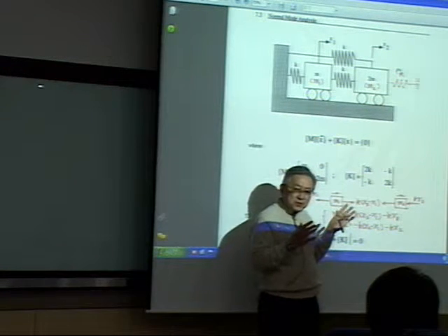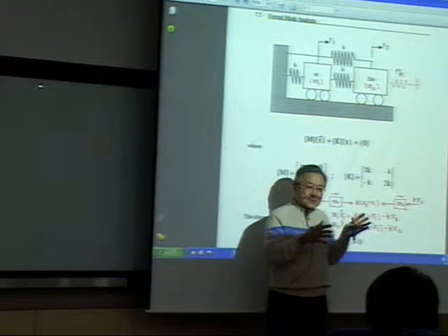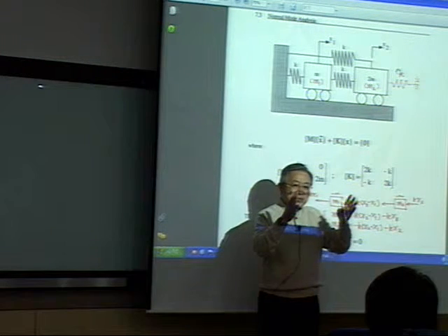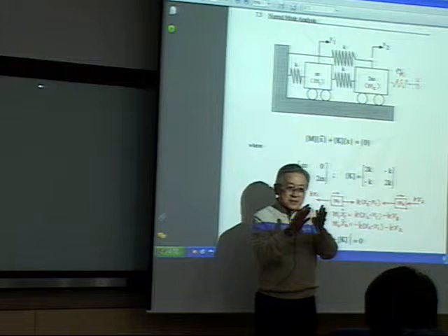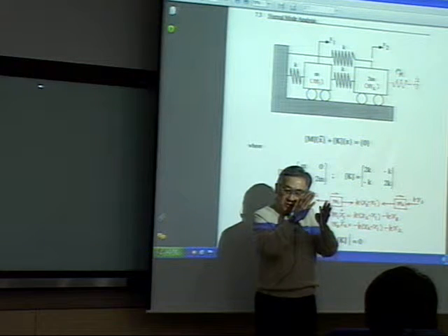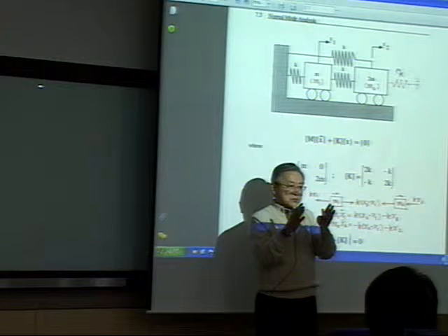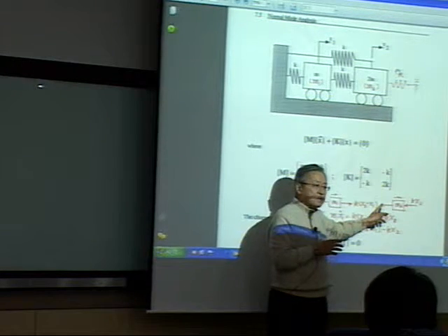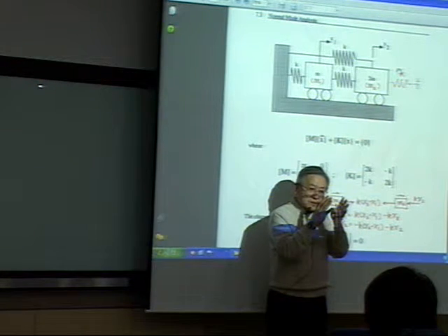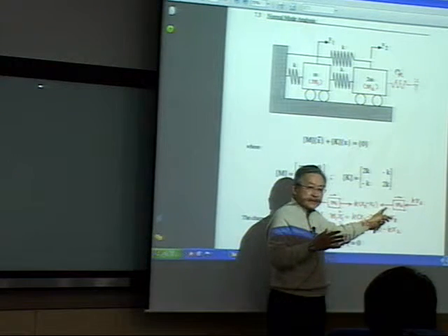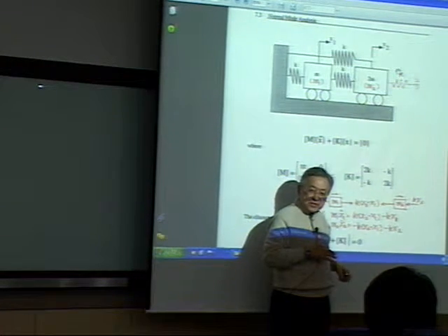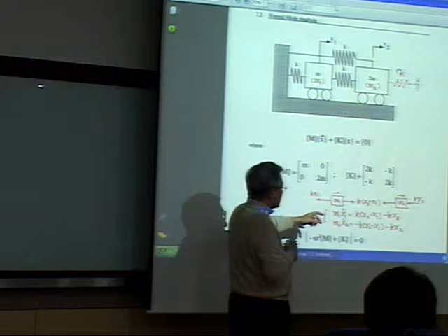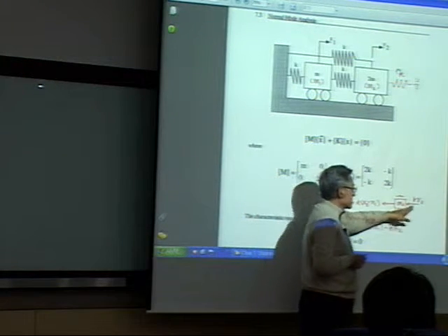And you can think the other way. You can solve it yourself. X2 is smaller than x1. Then the spring is going to be compressed. So that case is x1 minus x2. That's a positive number. Then the direction of the force is opposite. This is in compression, pressing. So you will end up having exactly the same result because of the sign as you're doing it. So now this is very clear.